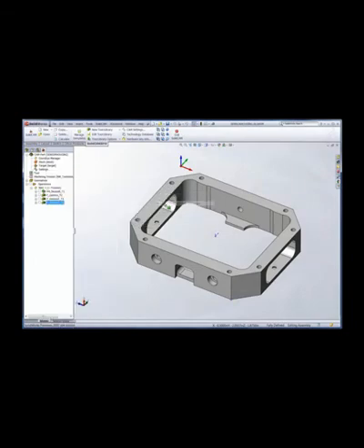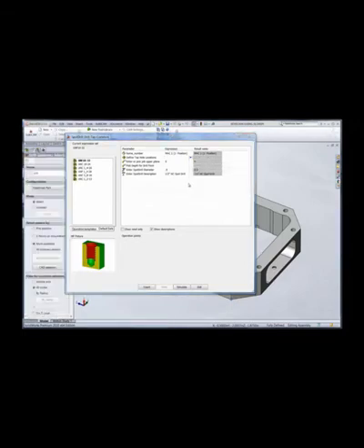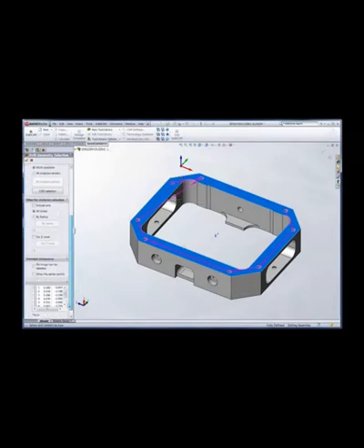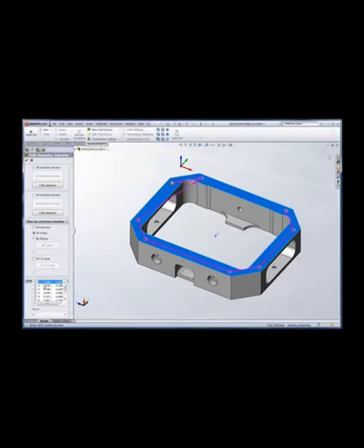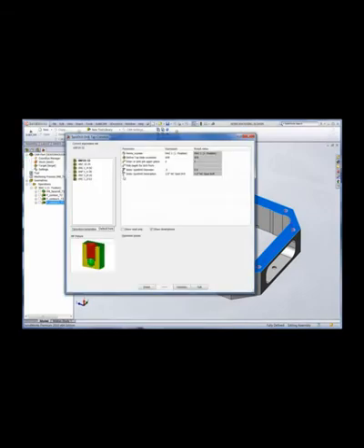From the CAM part definition, right-click, Synchronize will bring the model, stock, and target into synchronization. Notice at this point, each of these 3 tool paths need to be recalculated. Right-click on the Operations node, Synchronize and Calculate All, and that's how quickly the system generates the new tool path. And as you can see, the tool path is now updated for the model change.